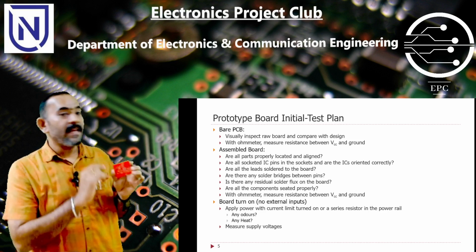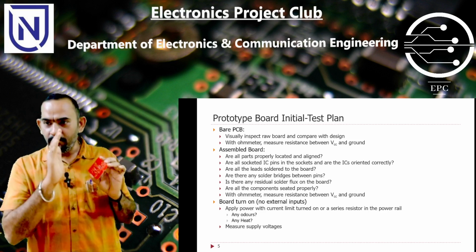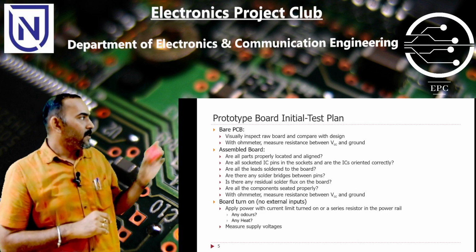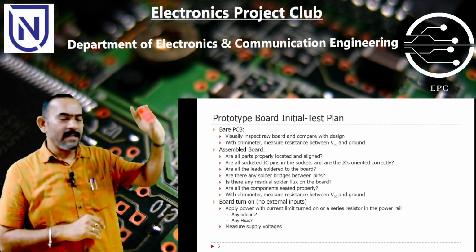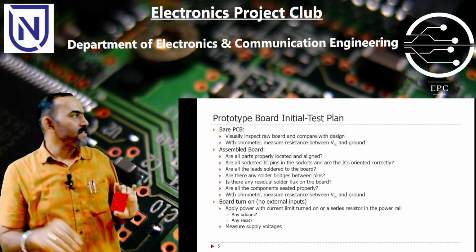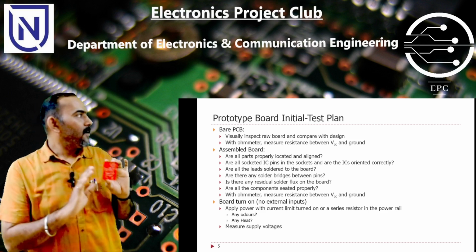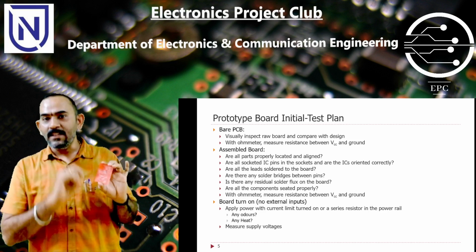So the first step is to ensure whether all parts are placed properly and aligned properly. This is the step we need to take. The second one: all socketed ICs, alignment and orientation is fine or not, all leads are properly soldered or not. Another one: are there any solder bridges?